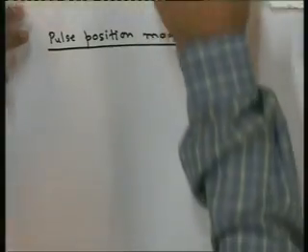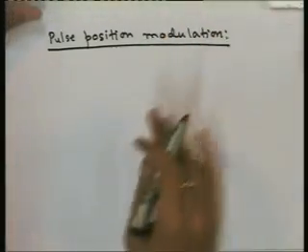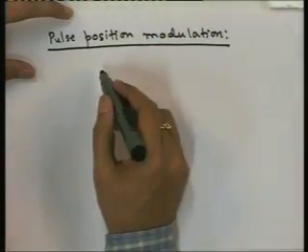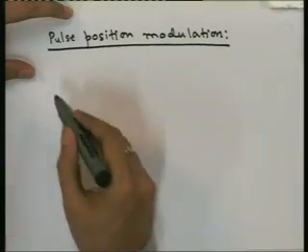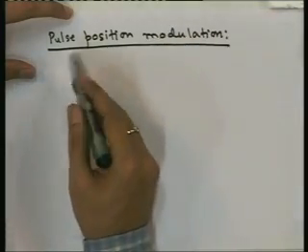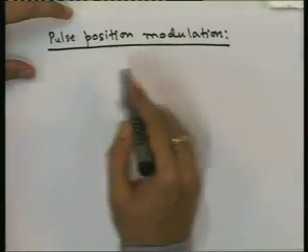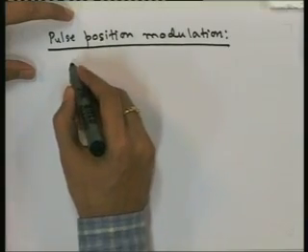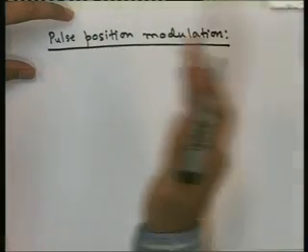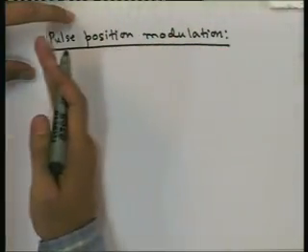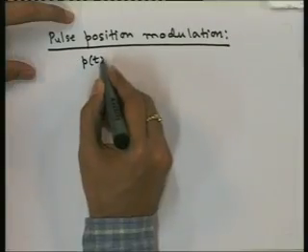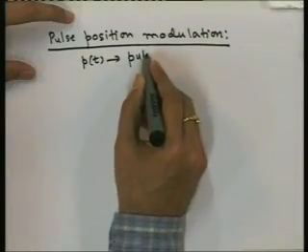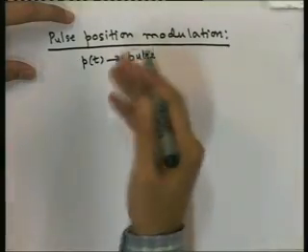We will discuss the baseband version of that, but it can be easily modified to have passband modulation. So it is basically the dual of FSK. In FSK we take different frequencies, here we take different times. So if you have a pulse p(t), if it is a baseband pulse, it will be baseband.